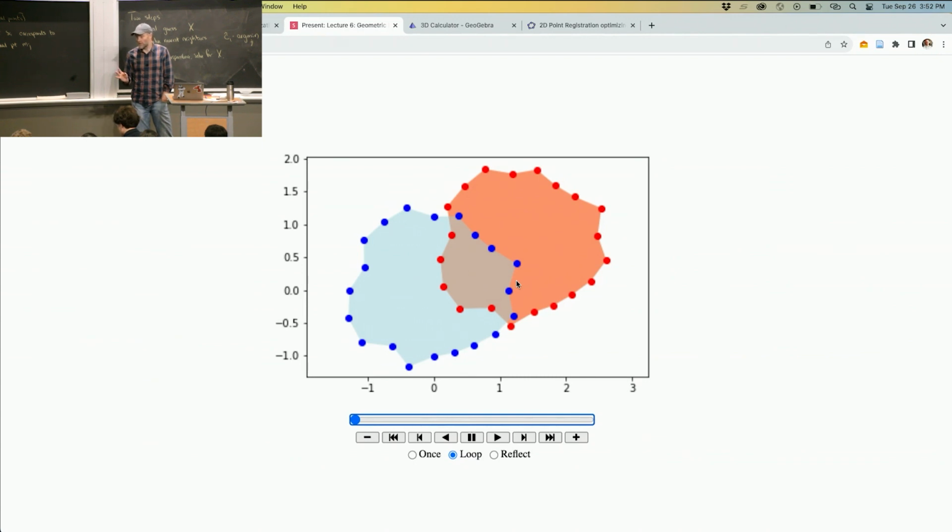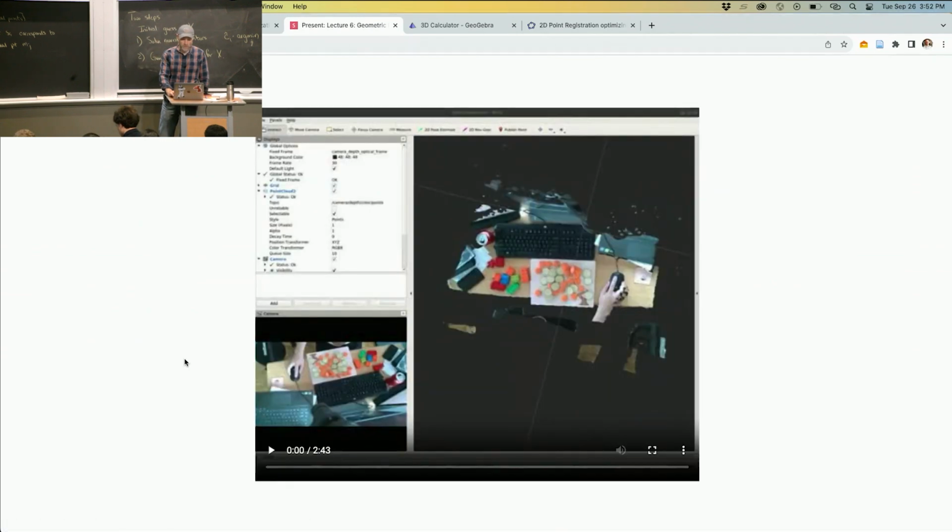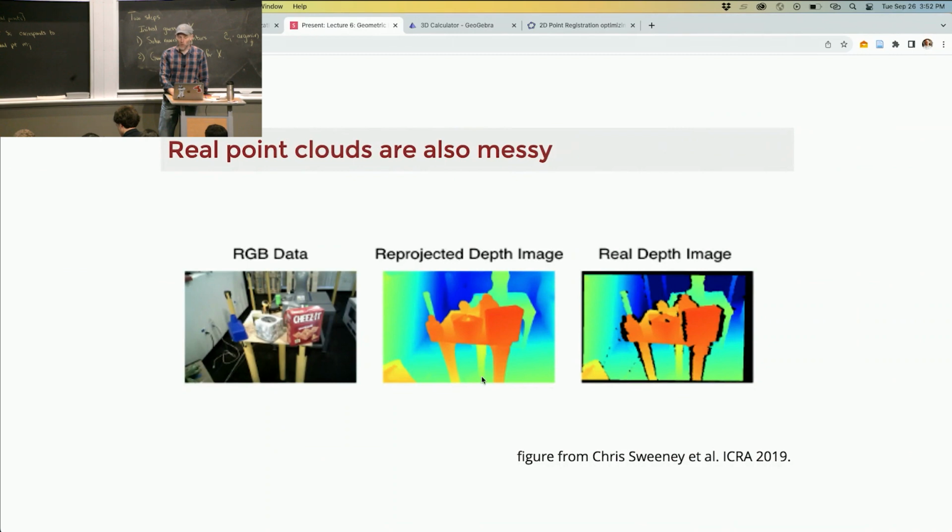And we're going to talk about noise also next time. It's a fairly subtle question, and I had a slide I blew past real quick, just to show you that real world noise is extremely structured. If you think about noise as adding Gaussian values to all of those values independently, that's not the way cameras have noise. This is the actual depth image, and this is the depth image you get out of a camera. They have dropouts, like pixels that are just missing in the middle. They will have swaths where, say, a shiny material might have very noisy readings, and a flat material might not. So the answer to your question requires thinking a little bit about the types of noise.